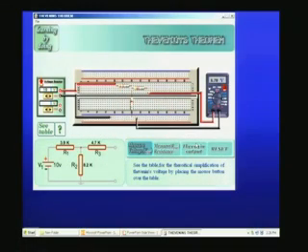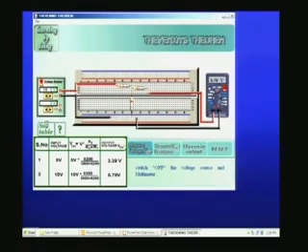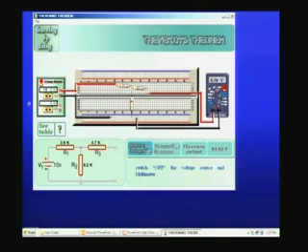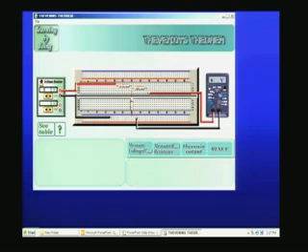If you want to see how it comes, you can go and look at here. You can see the whole thing. If I apply 5 volts, the Thevenin's equivalent voltage will be 3.39. When you apply 10 volts, the Thevenin's equivalent is 6.78. Now we will switch off the voltage sources.